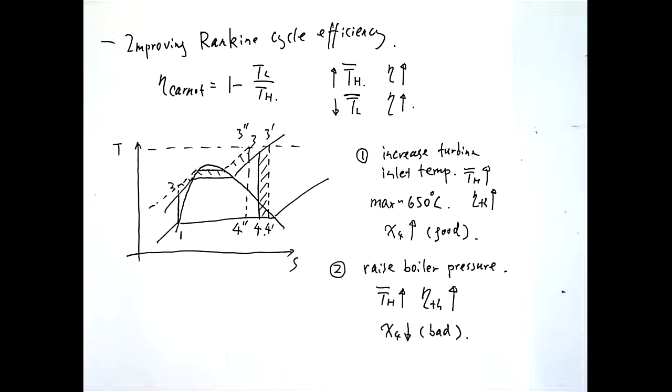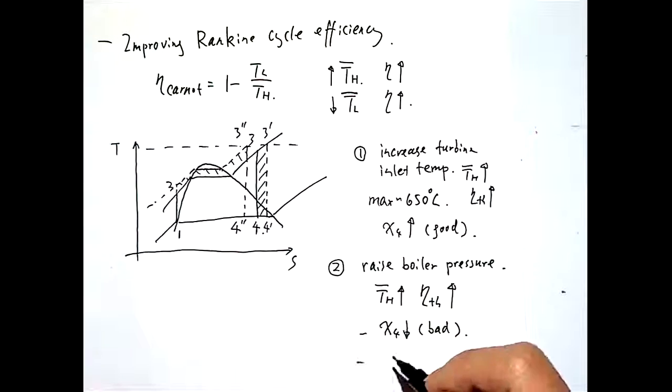Also, when you're increasing the pressure of the entire system in industry, high pressure means high cost. As I said, the pressure is equilibrated across the entire equipment or entire system. So everywhere you need to use a high pressure rating, or material rated for the high pressure, in order to handle the whole thing. And also the temperature is higher. The high temperature, high pressure will require the system to use more expensive material. So that's not necessarily desired. It's more costly.